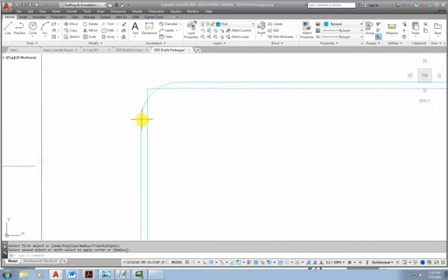And so we can either change the fillet to 2 feet 6 inches, or we can offset. So it would be easier to change the fillet radius, but I just want to show this technique. And so I'll say offset 6 inches, and you can see it comes in right where it's supposed to be. And then I would have to trim it. And if I hit enter, everything's a cutting line, which means I'll have to do a little bit of cleanup work.